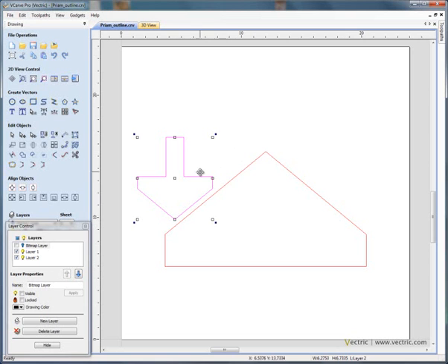But one of the challenges here is that although it's relatively easy to calculate this smooth surface, there's a lot of material in this triangle area here that first needs to be removed to allow that edge to be formed by the cutter. The raised prism machining toolpath automatically takes care of this for you.